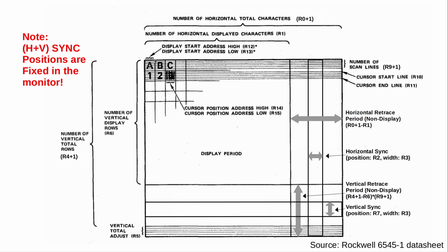And that depends on the region. So for example, in 50 Hertz regions we have 50 cycles per raster line and 400 raster lines to get a screen refresh vertical frequency of 20 milliseconds or 50 Hertz. For the 60 Hertz regions, it's different. So the NTSC timing, for example, is 64 cycles per raster line and 260 raster lines, I believe. So as long as you keep that overall timing, the machine should really sync to that signal.